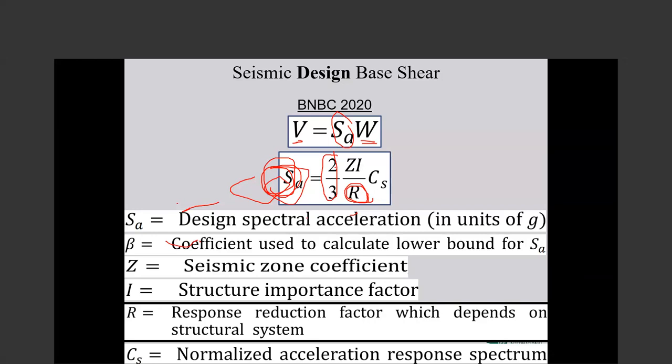For example, if we want to model a building for damage, and a reinforced concrete column or beam can be damaged in shear, it is very difficult to model the interaction in a column between shear, axial load and moment.